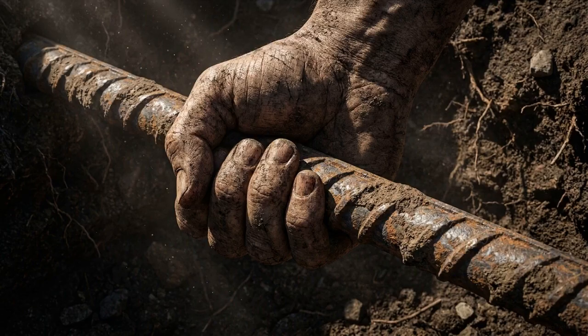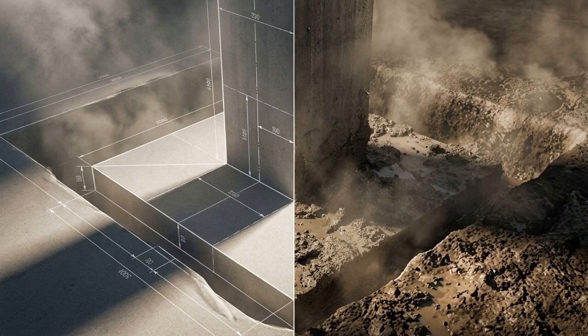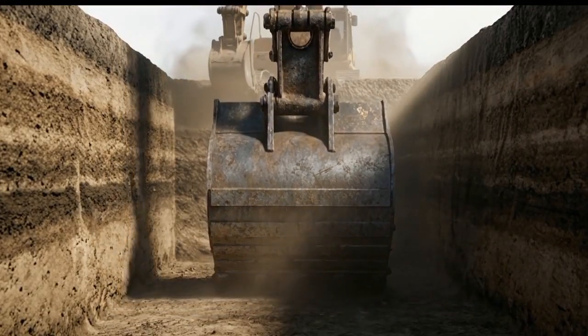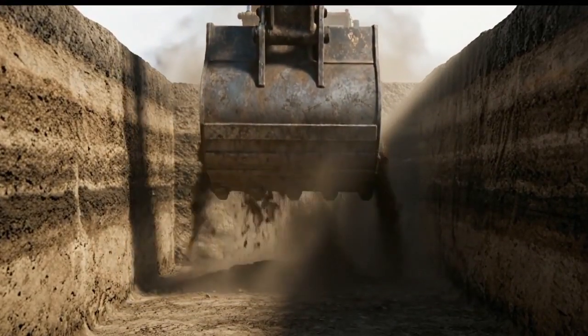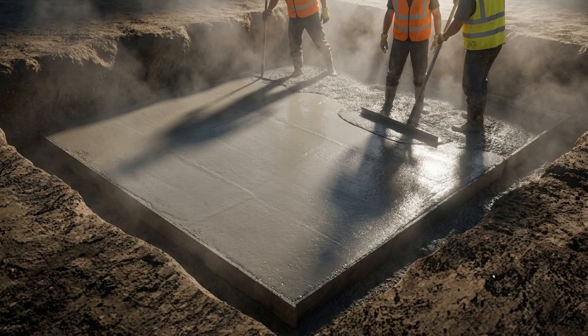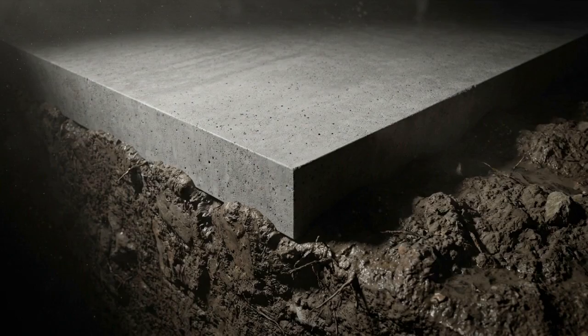But all of this calculated theory is useless until it is physically built. Brilliant structural theory is instantly compromised by flawed construction practices. Execution on site must be exact. It starts with rigorous site investigation and surveying, followed by precise excavation. Crews must dig to the exact depth to reach the approved bearing soil. Next, workers pour a leveling course of plain cement concrete, or PCC. This creates a clean, flat, hard barrier so the structural foundation never touches raw dirt.